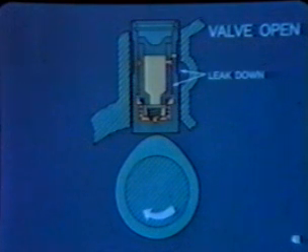There is a very small amount of oil leakage past the plunger to prevent the lifter from pumping up. It is critical that the plunger leak down isn't excessive, or the valve won't open enough. Conversely, not enough leak down will hold the valve open. Hydraulic lifters usually are tested for leak down before installation in the engine.